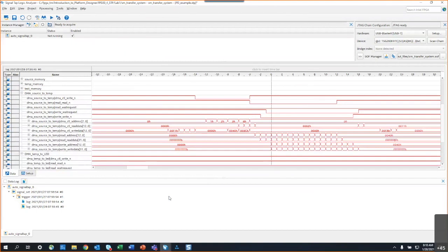Then we had another question. So what is the rule of thumb for the clock? Is 2x a good option for the sampling clock? That is a great rule of thumb. That's the recommended sampling frequency, to try to sample at 2x whatever speed you're trying to look at. So if you do have that clock available to you, then definitely use it.